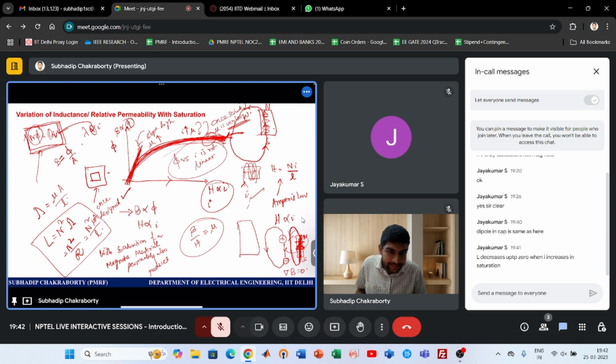Frequency is also very important for which you design that material. And that's why we say that with increasing frequency, the inductance or the size of the inductor reduces. That is also a perspective. And for a given frequency also, your current variation will change the saturation level, which will completely change the magnetic characteristics of that core, in turn, which also practically affects your inductance value. So things are not very trivial, how they look in the relations and in the formulas, right?